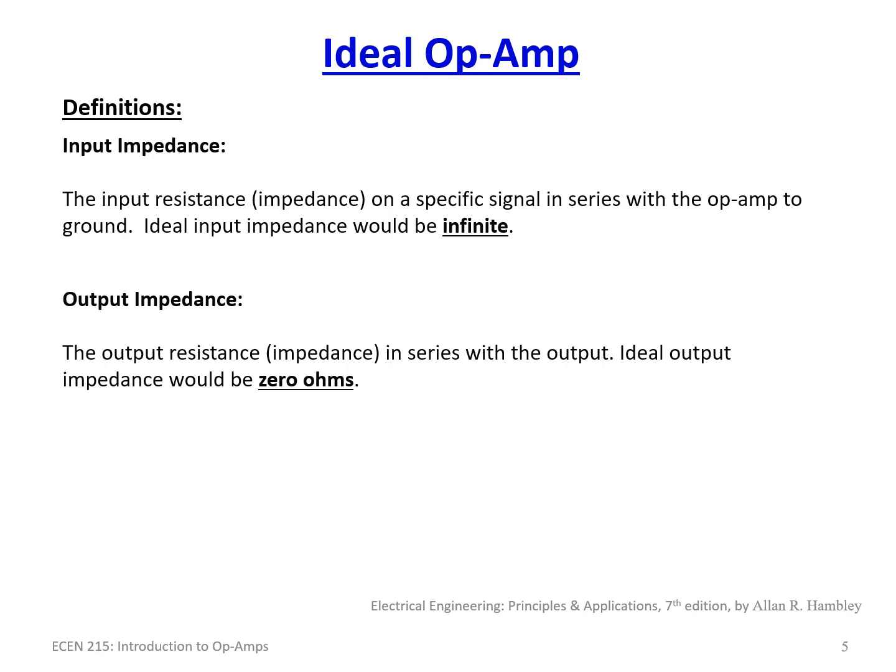And the output impedance would, in theory, be 0 ohms. I would want to drive the output to exactly the voltage I'm setting and always maintain that voltage. So think of this in terms of the Thevenin circuit that we've gone over multiple times in this class. Here we have a power supply that, in the case of the output, would be the output resistance.